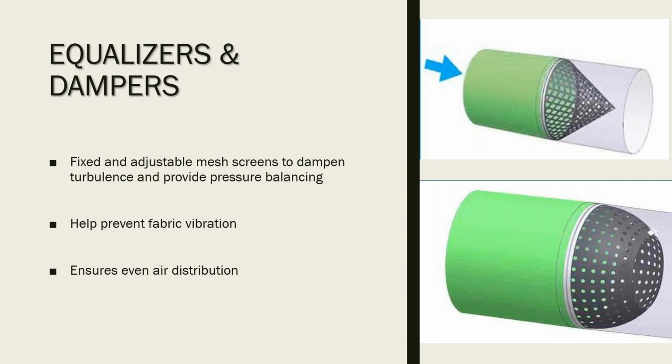So let's just say you have a project where the metal prior to the fabric, because we can only do fabric in exposed locations, so any metal prior to the fabric, let's say beyond the wall or above the ceiling, is not made in the correct size as far as radius elbows, or we don't have enough clearance as far as metal ductwork prior to the fabric.